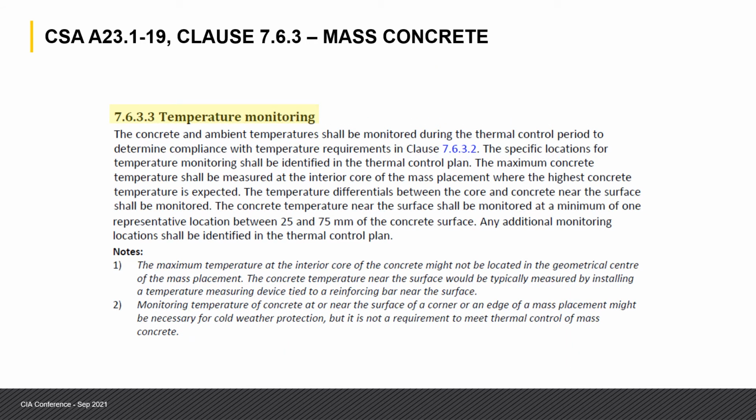One important part of mass concrete is temperature monitoring. Something that we did here is at least put a brief description of the basics of temperature monitoring that we need. The temperature monitoring in the interior core, where we can expect the highest concrete temperature, and then the concrete temperature near the surface needs to be monitored at a minimum of 1 location between 25 and 75 millimeters from the concrete surface.